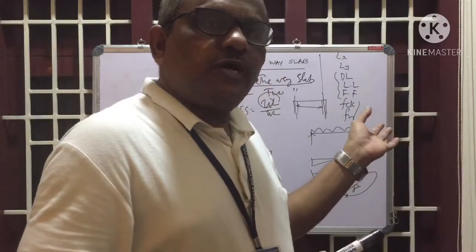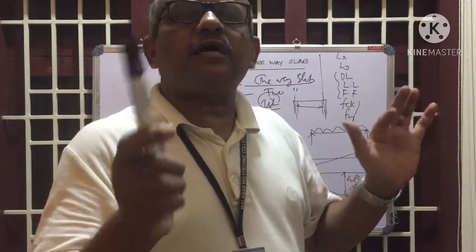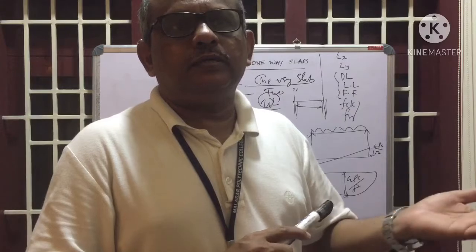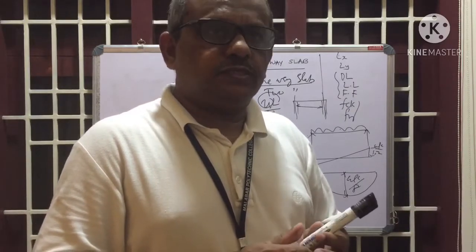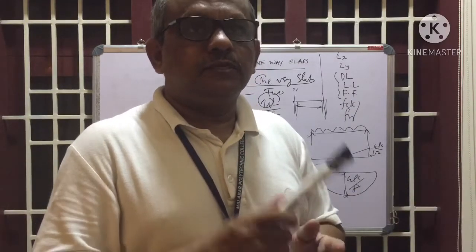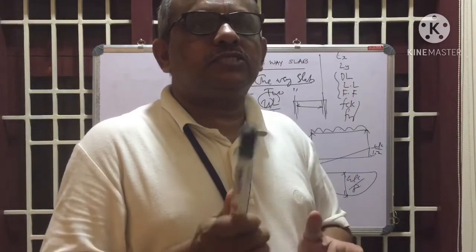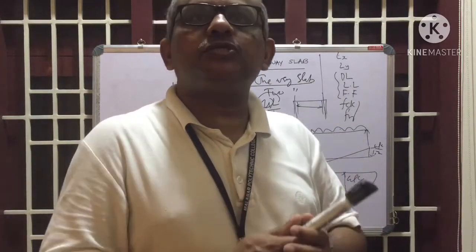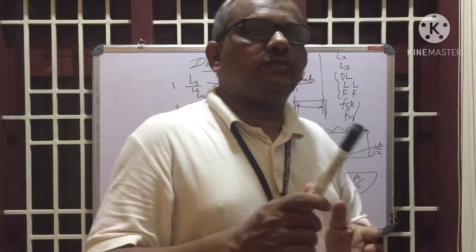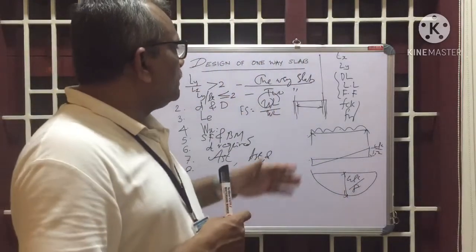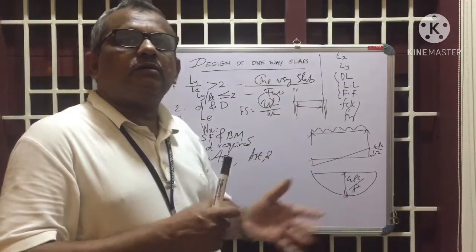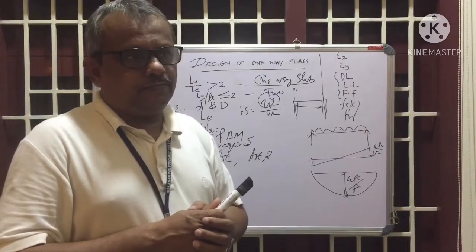From the maximum SF values, get nominal shear stress and design shear stress, compare and design the reinforcements, the number of bars and diameter. Similarly, deflection depends upon the stiffness. So the L by D ratio is to be calculated and checked with the parameters in the code, to see whether it is sufficient or not for that particular slab.